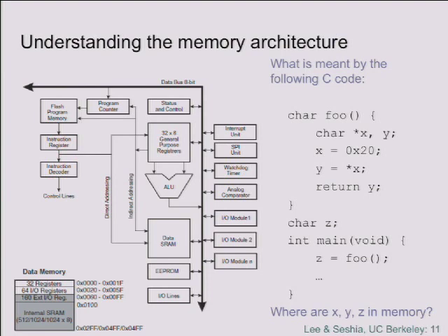Yeah, you'd have to specify the address. You'd have to know where in your address space the program memory is. And then you have to make sure that the compiler doesn't use that address that you just used for your variable in some other way, okay? So it could be kind of tricky to force this thing to go into program memory. By default, it's almost certainly going to go into your data memory.